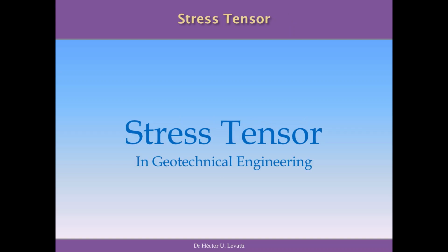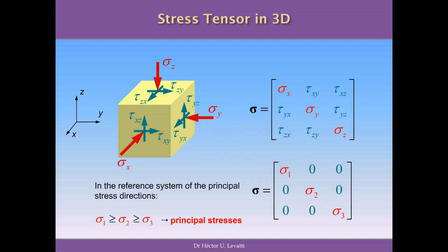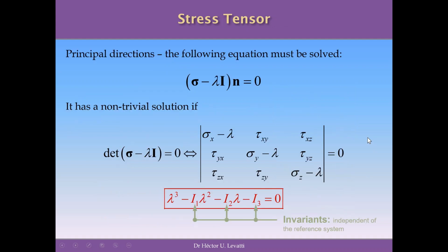Let's talk a little bit more about the stress tensor in geotechnical engineering. So we said that the stress tensor is represented by a matrix, that this matrix is symmetrical regarding the diagonal, and you can work out the stress tensor considering the principal stresses that are in this order by convention. But there is more to say about the stress tensor.